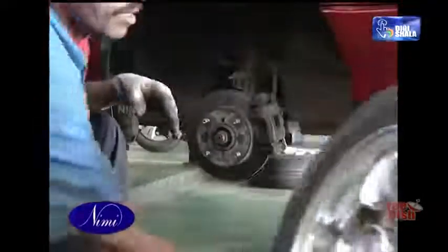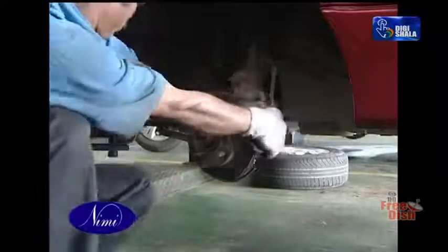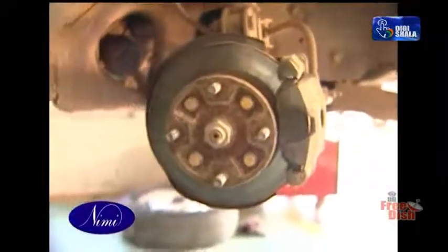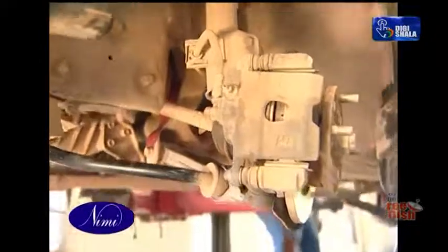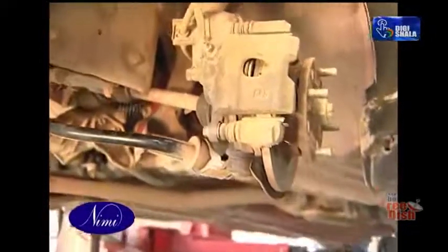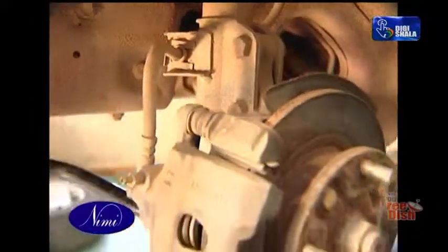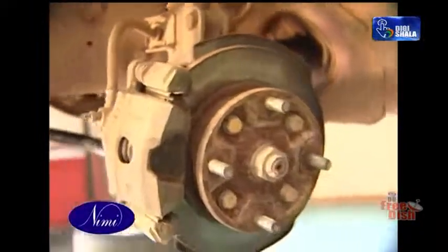Disc brakes. Exposed to the air, disc brakes radiate the heat to the air better than drum brakes. This means that the brake can be operated continuously for a long period as they have a greater resistance to fade, or in other words, fall off in brake efficiency due to heat. This fade resistance and features such as automatic adjustment make the disc brake a popular choice for the front wheels of a car. A vacuum servo fitted to the discs boosts the effort applied by the driver.